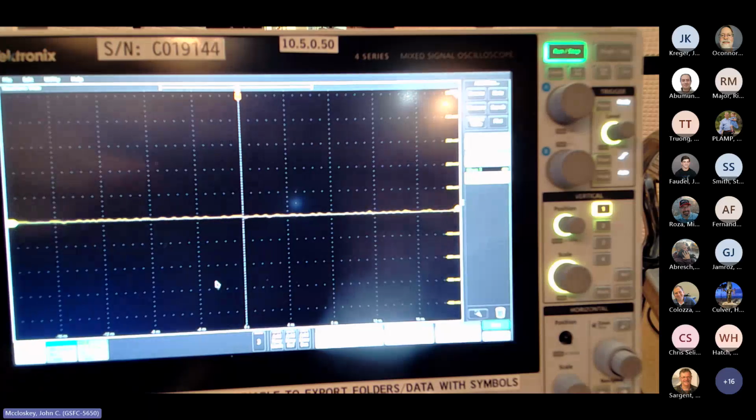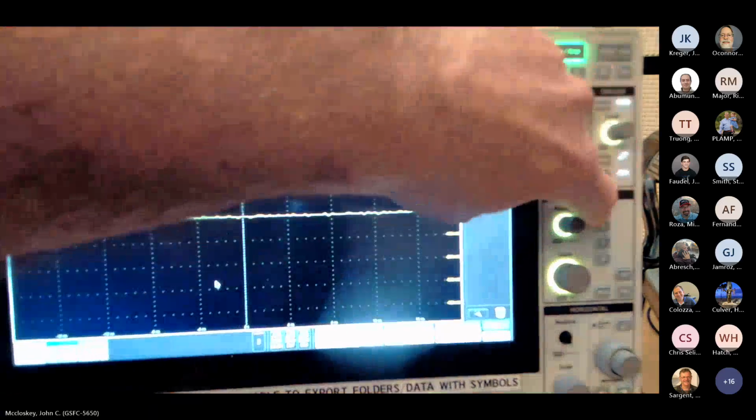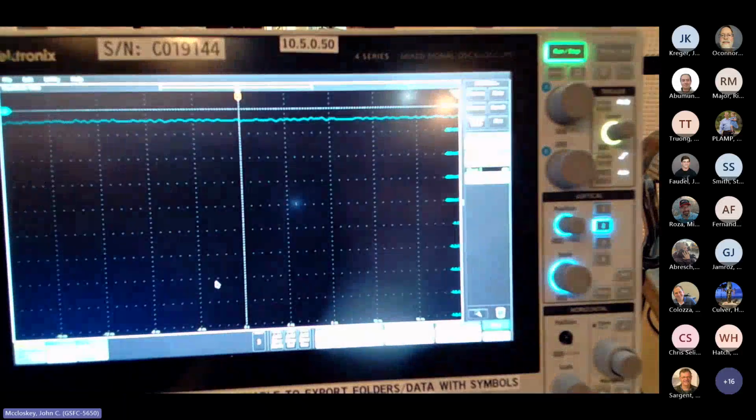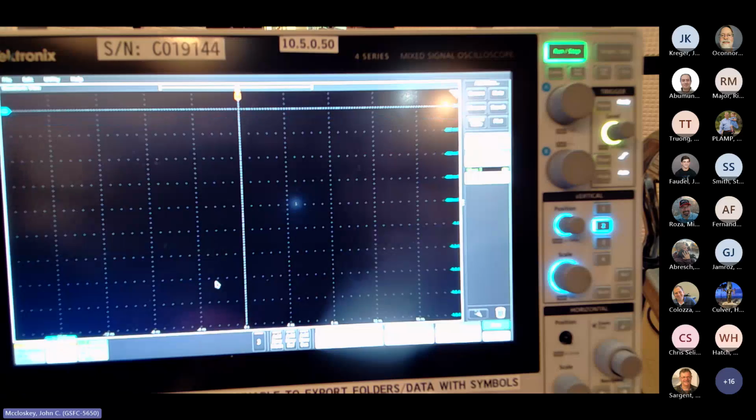So we're not looking at channel 1 anymore. We're looking at channel 2, and these Hall effect current probes. It's sometimes very hard to completely get rid of a DC offset. You see there is a little bit there.